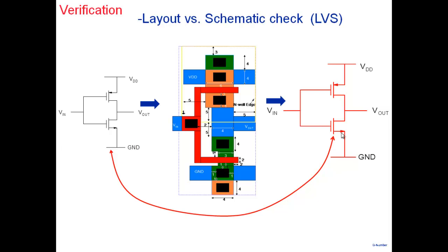The new schematic is compared with the old schematic. Do we have a PMOS? Okay, we have a PMOS here. Is it connected to VDD? All right, so this is connected to VDD. Do we have an NMOS?